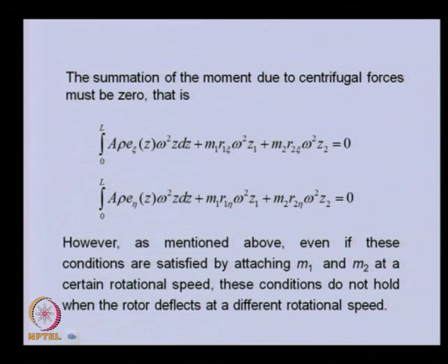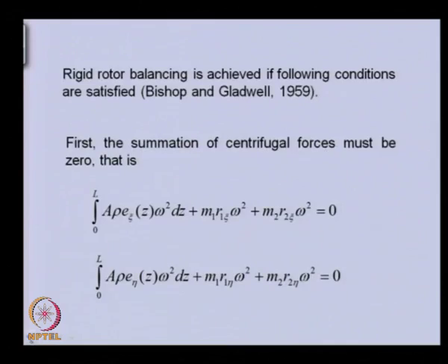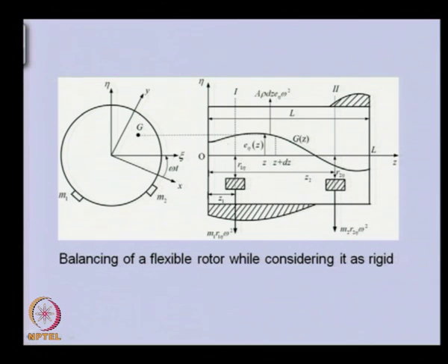Now, to balance such a rotor in which there is continuous variation of the eccentricity, one way we can do it theoretically is to put some kind of continuous mass here. You can see the shape should be the same, maybe the height may be different proportionately according to the radial position of the correction mass.